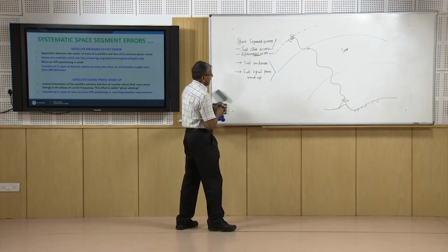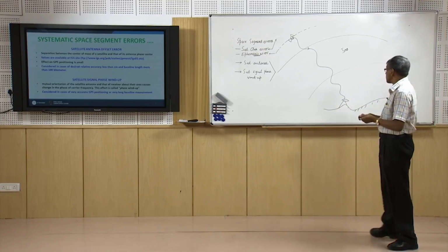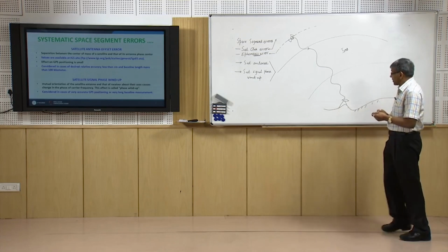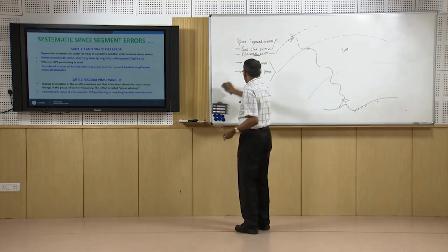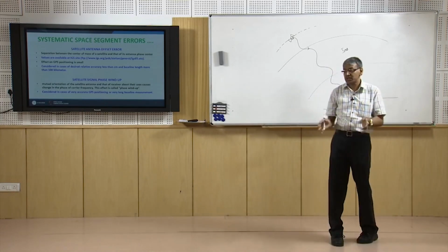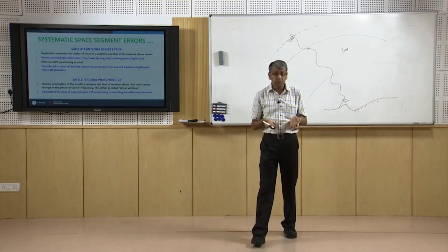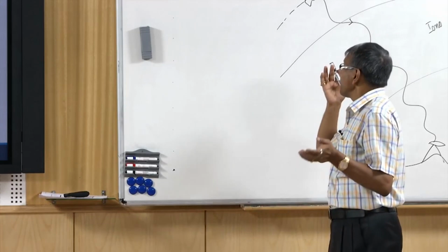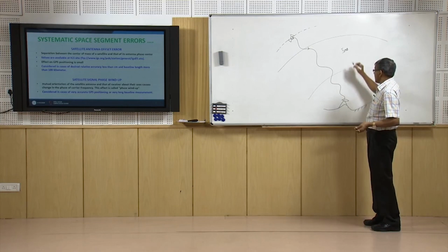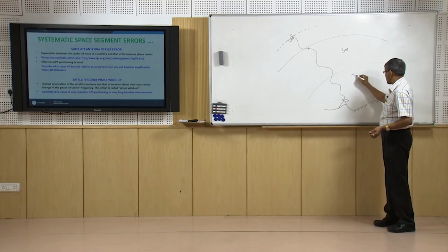Now, as the signals come from the satellite through the atmosphere, during propagation the velocity of the signal as well as the nature of the signal will be disturbed. Specifically, the velocity will be reduced and the signal will get dispersed in the ionosphere, and it will be physically obstructed or deviated in the troposphere.